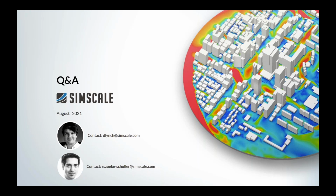We also have a single directional analysis, which is called incompressible LBM, which is the same technology, but you have more freedom, but you don't have the statistical analysis, and there you can run many more at the same time. That's up to you. There's basically not really a limit on the number of directions, but 36 is what we can do with the pedestrian wind comfort study, and as far as I know, there's not really a need to run more than that.